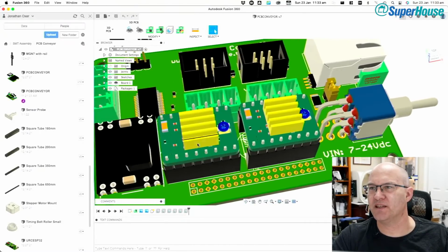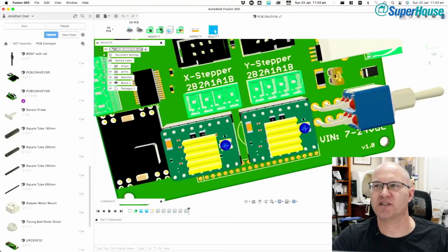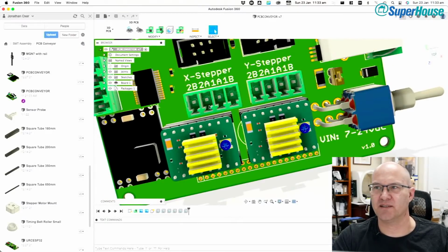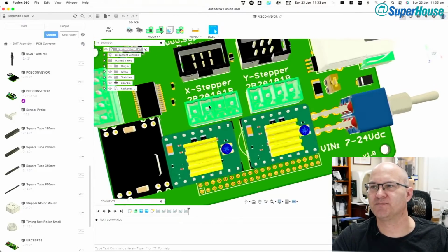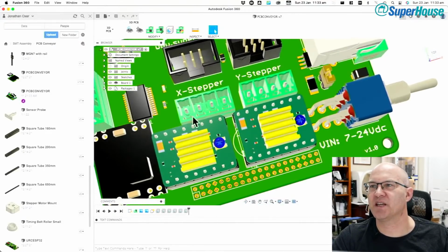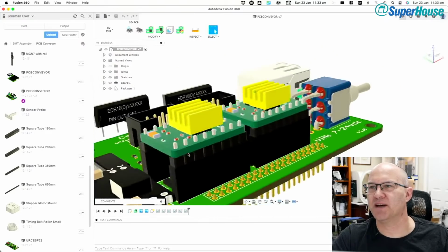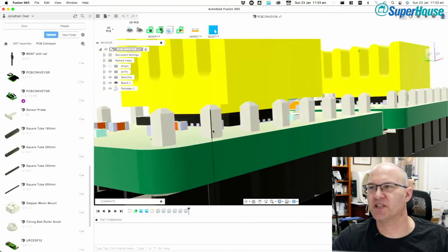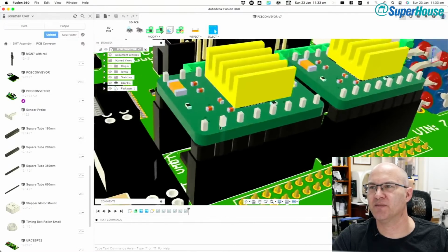And then the other output, we can change this to drive a solenoid, essentially like a DC motor, by replacing this module. So when you're driving a stepper, typically these will have a little stepper motor driver chip on them under here, under that big fat heatsink.